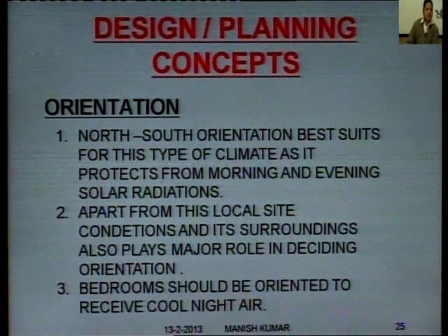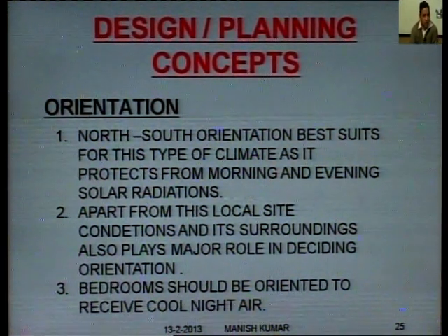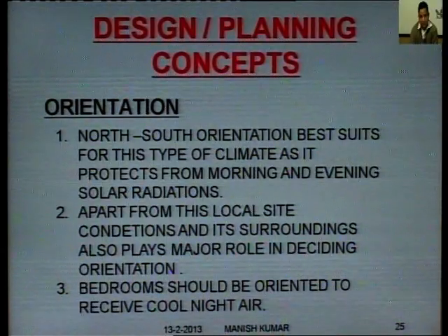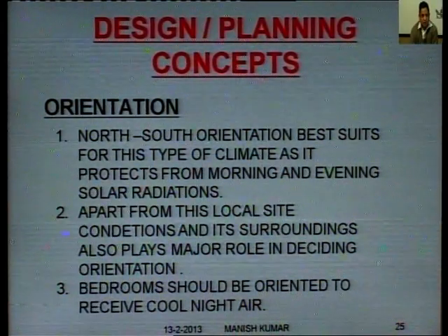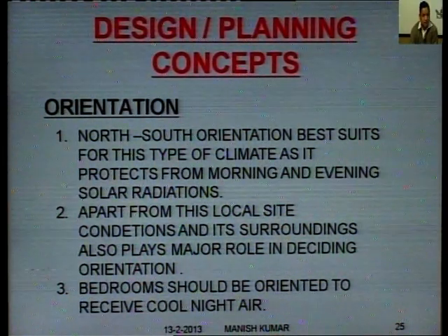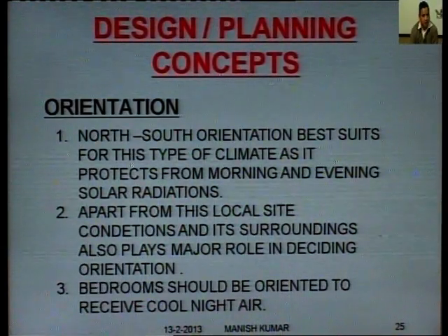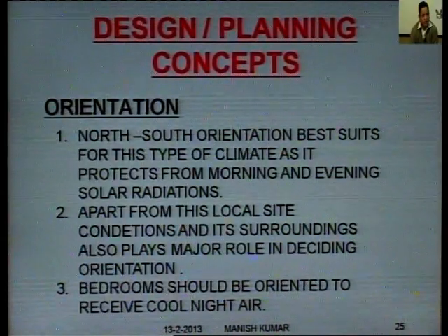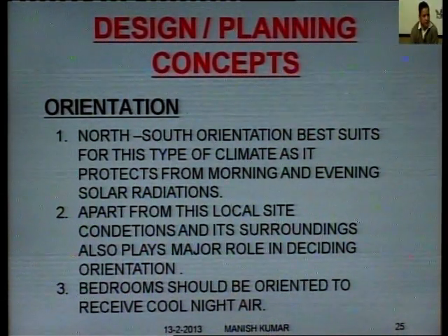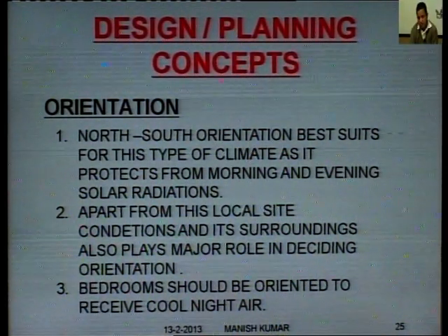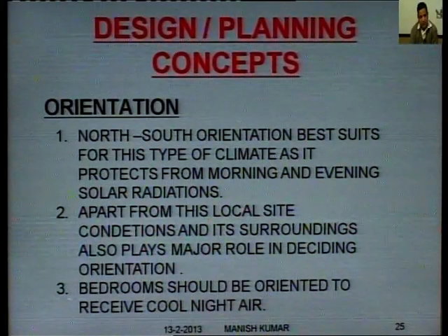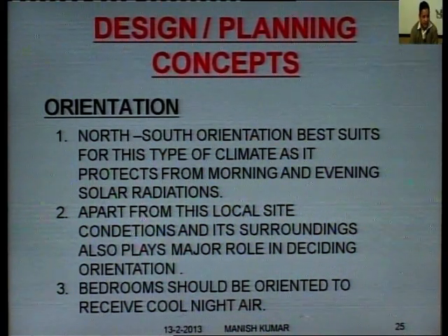Next is orientation. Orientation means how we should place our buildings. The first point is that north-south orientation best suits this type of climate, and it protects from morning and evening solar radiation. So the best orientation for this type of climate is north and south, as it will protect us from the morning and evening sun.